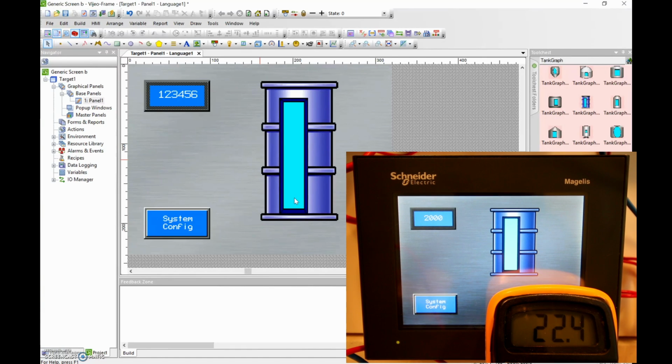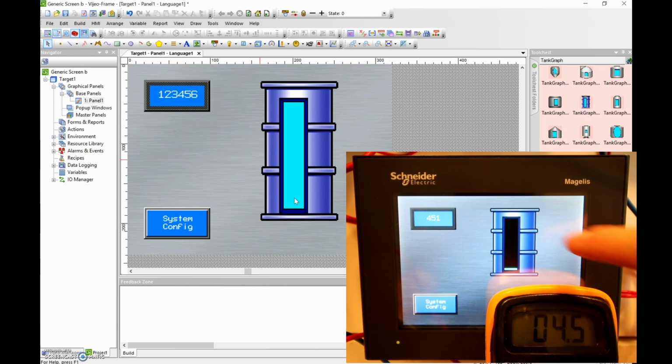into my HMI, and if we take a look here and I change the signal, then the value should start to go down. There we go. All the way down to 4 milliamps. Now I'm using an inductive sensor, and the piece of metal that I can press up against the sensor gives me the smallest value of 4.5 milliamps. But you can see here that the value is identical between this guy right here and the value that we're seeing on the meter right here.